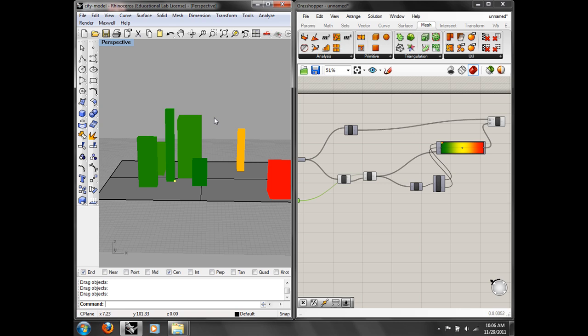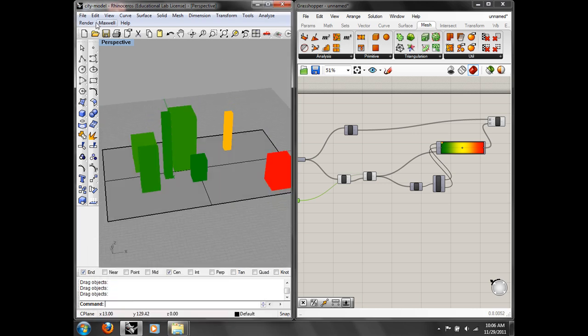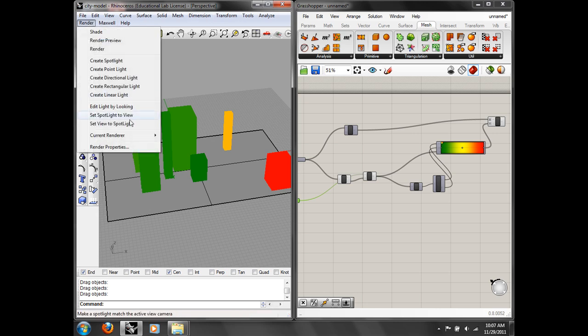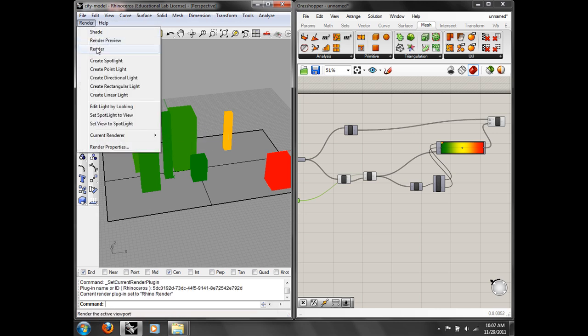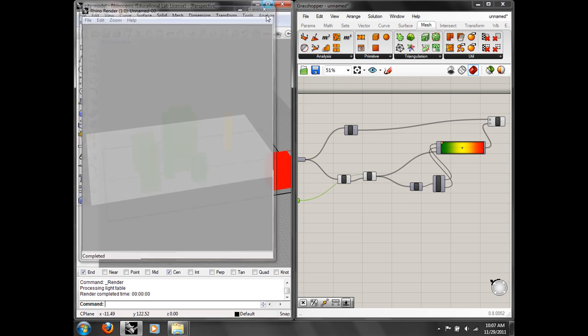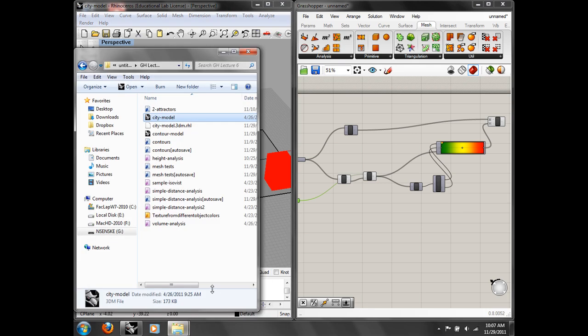To get it out, I will post a component. You can't render this, at least not right now. Maybe in a future version of Rhinoceros. Well, you can't render anything until you bake it. But if you bake this, you don't get the color right now. There's a component that I would give you that basically transfers the mesh stuff to a texture and then automatically applies it.